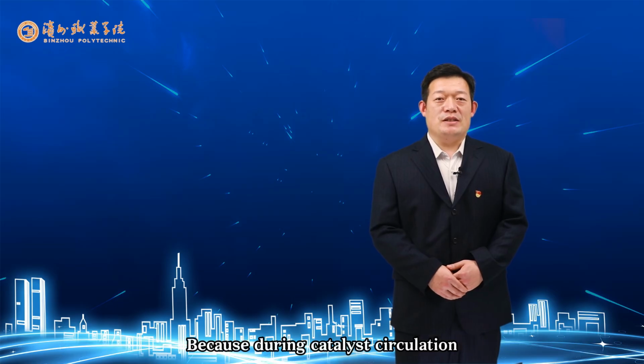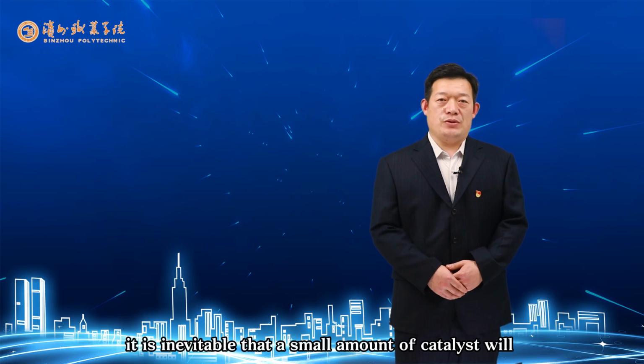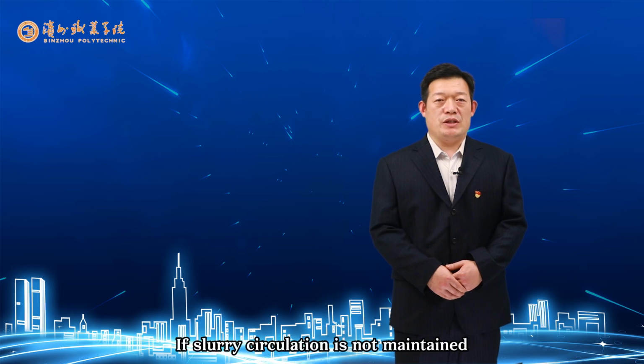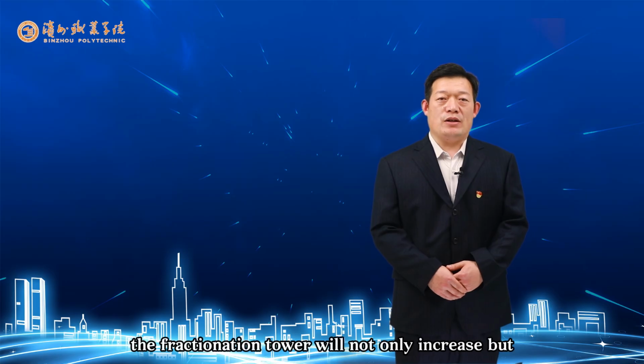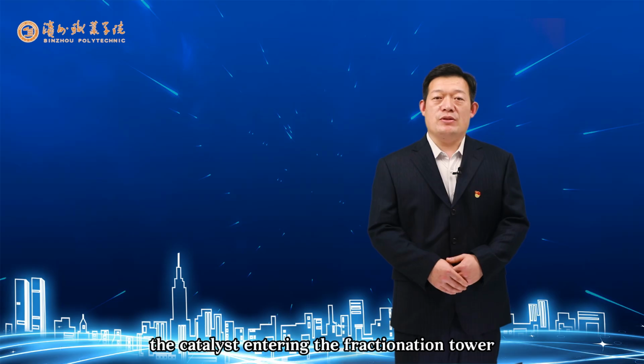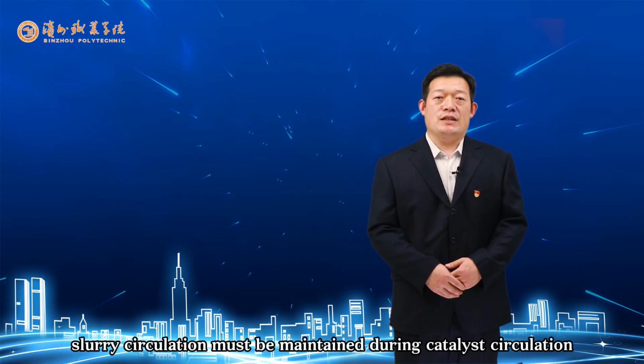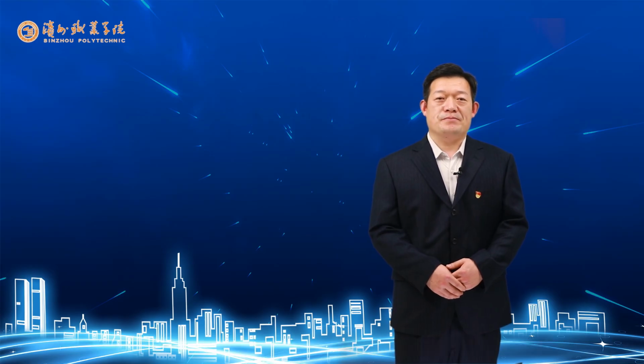Why? Because during catalyst circulation, it is inevitable that a small amount of catalyst will carry over into the fractionation tower. If slurry circulation is not maintained, the solid content in the slurry at the bottom of the fractionation tower will not only increase, but the catalyst entering the fractionation tower will also migrate upward, clogging the trays. Therefore, slurry circulation must be maintained during catalyst circulation.